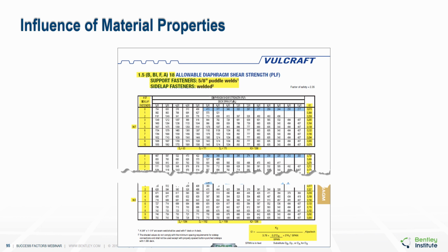You can have different conditions, which mean you have a different G prime, which means you have a different E effective. And technically, to be 100% correct, you would have to model each different area of diaphragm with different values. Is it reasonable to calculate a representative value and just use that across the entire diaphragm? Is the influence of these material properties that great on the distribution and on the diaphragm effects that it's important?